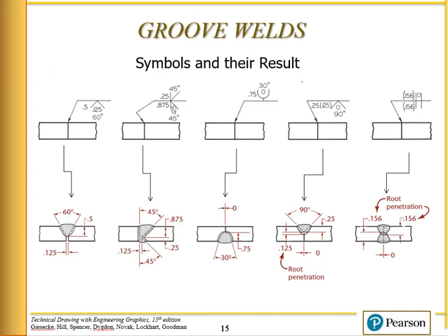Okay, let's talk about groove welds. Groove welds are used to make a stronger joint. What they'll do is prep the surfaces and edges of these materials. You'll come in with this butt joint, and they'll grind these edges off so you can lay a bigger bead across.